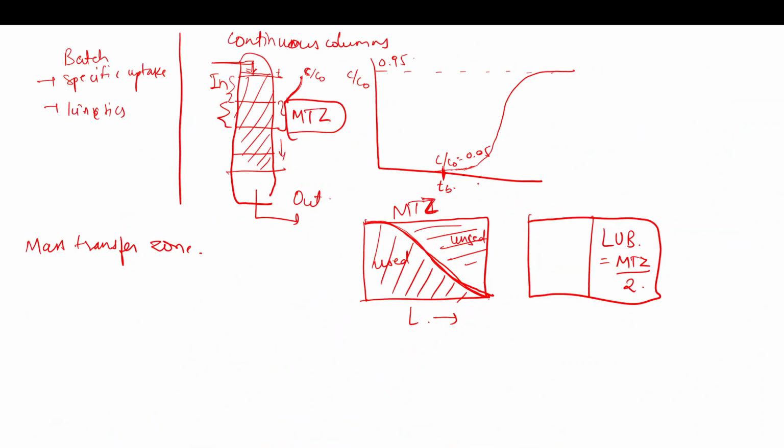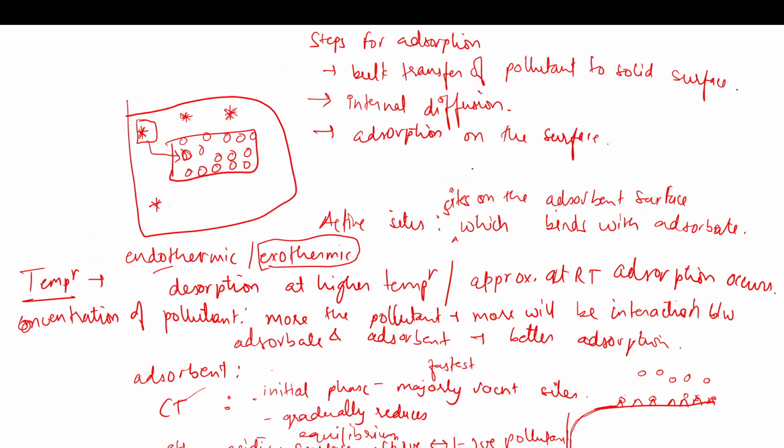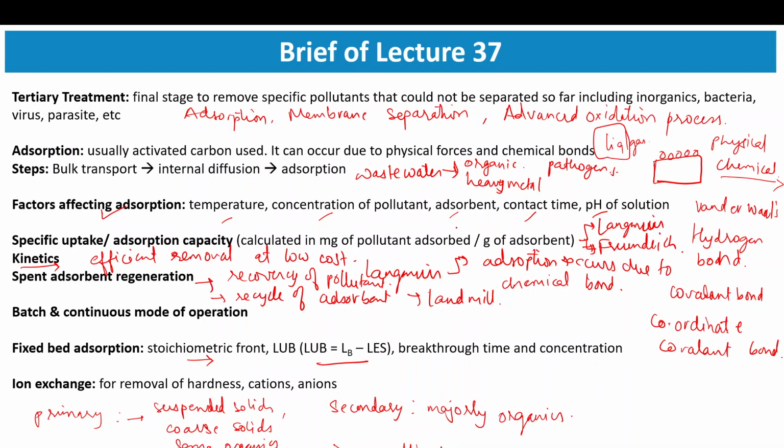Breakthrough time I have given you is the time after which the pollutant starts appearing in the effluent, and the concentration in the effluent per unit inlet concentration is 0.05. Okay, so these calculations are important for adsorption process and especially for fixed bed adsorption.